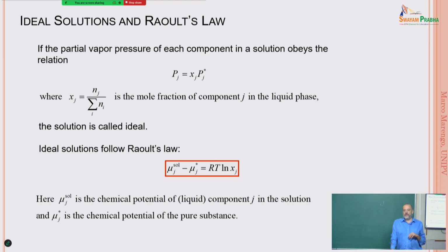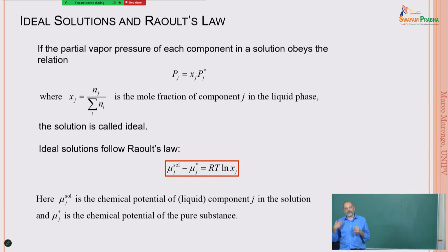A classical multi-component problem in a heat pipe is that inside the fluid you have dissolved gas. You have the liquid, or you are using, for example, ammonia, water, propane, acetone, whatever. But some air gas is inside. You did the vacuum, you tried whatever, but some gas is there.